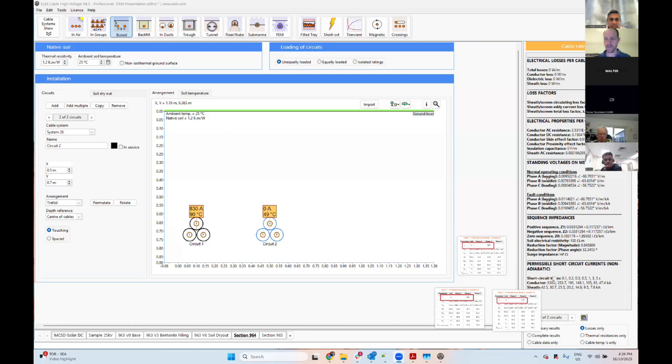The 3D FEM compared with the 2D can definitely require more computing power. If we are going to plan for this project, we need to take care of this and consider it more carefully. So with 3D FEM, in theory, you can better model mutual heating and longitudinal heat transfer along the cables. Potentially, yeah. It's a project of ours that we will undertake.